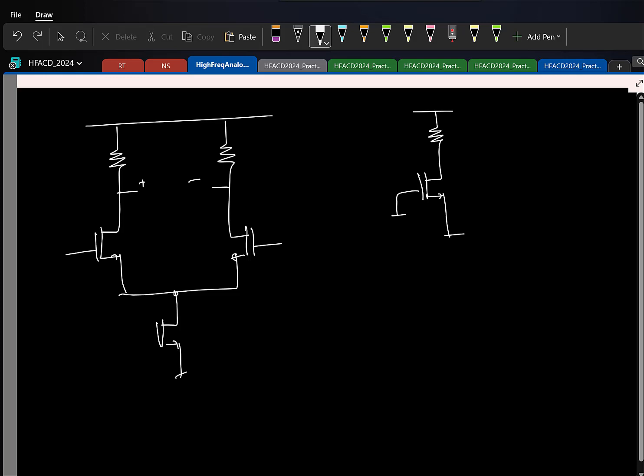Just this, right? For this you try to find the input referred noise PSD. Can you tell me what that will be? Let us say this is RD, this is M1, and let's say SVn of f. The transistor's noise is going to directly come, there should be no confusion.